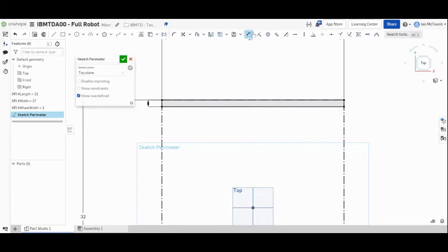So I have now set this rectangle is fully constrained because you'll see when I hold my mouse over here, this point has to be touching that line. So that's the coincident. So that point is touching that line. And if I hold my mouse over that, you can see they're highlighted. So that's highlighted. So that forces this to be a certain length because that point has got to be touching that line as well. So there we go. That's that point right there. And I've set the distance between these two lines to be 1 inch. So that's why that's black. It's fully constrained. That's great.